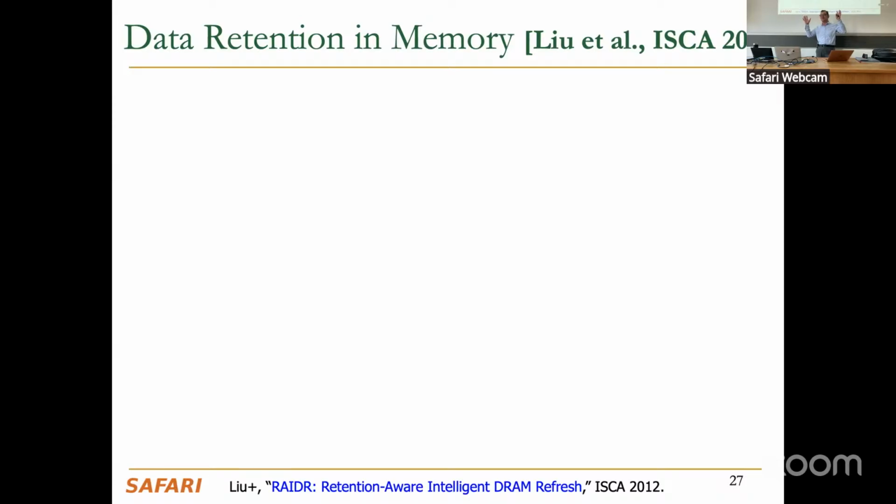This is all intuition. You can model it in simulation also, in circuit level simulation. The question is, is this real? What measurements can we do on real DRAM chips to understand how bad this problem is? That's the reason why we built this infrastructure. You're going to see more of that later on. And one of the things we found using this infrastructure is that not all cells are equal. The common practice in how you retain data in DRAM today is, because DRAM leaks charge, you need to refresh cells periodically. Refresh meaning you basically inject charge back into the cells.